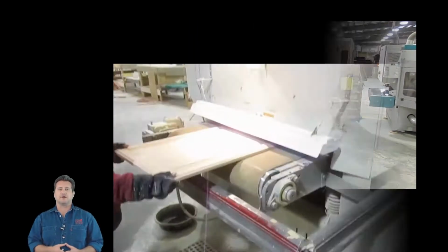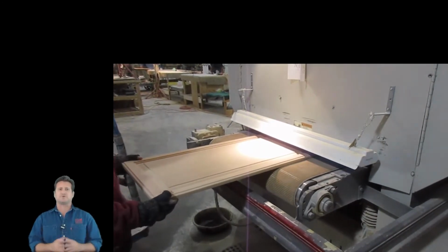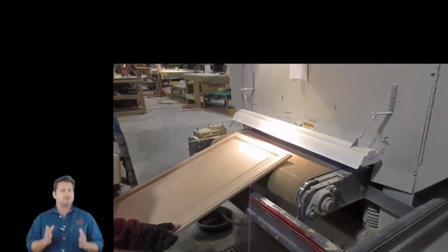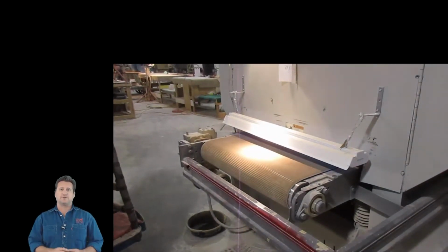The next sanding process is a double head vibrating sander which removes any cross-grain scratches left from the prior triple head sander. The output of this sander is equipped with an ultraviolet detector which illuminates any glue or oily fingerprints on the door. Although not common, fingerprints do happen and we want to find and remove them so you won't need to.